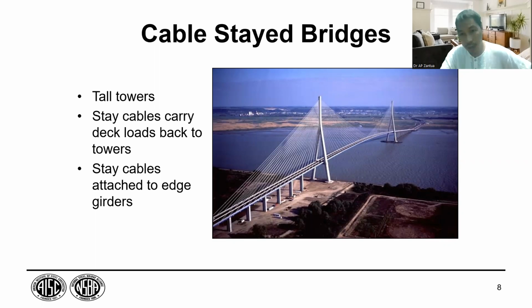It is even more economical to use this rather than to put up several piers in this area, because it is always expensive to put up columns or piers coming out of the bottom of the river or the sea. It could be done, but it is more expensive.